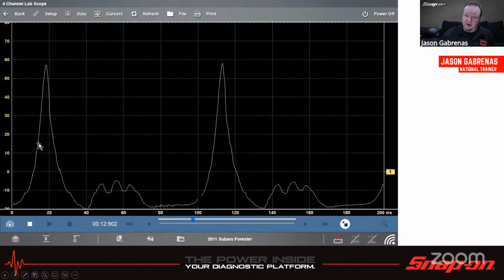So the compression comes up, and then the piston starts going down. We're on the expansion stroke here, on the power stroke. Then you should see a vacuum pocket. Then you're going to see your exhaust. Then you're going to see the intake valves open, and then you'll see a vacuum again, and then you'll see compression, and then you'll see it drop back down there.